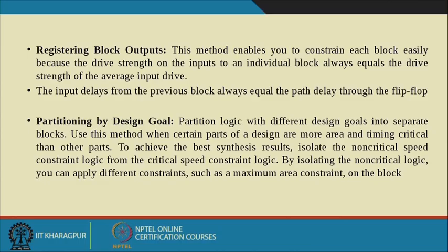then again we can do this: registering the block outputs. Okay, then the outputs will be registered, and then partitioning by design goals. That means each block's specification, like the adder design and the multiplier design, the corresponding performance of these two blocks is different.